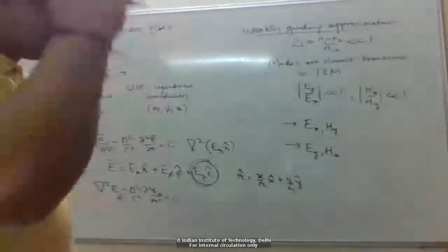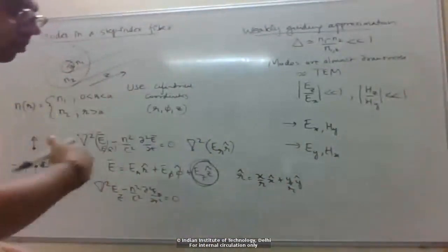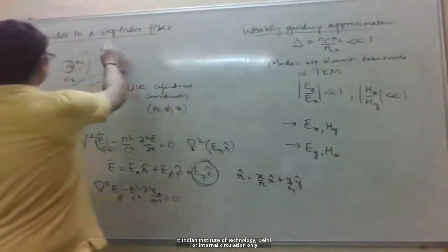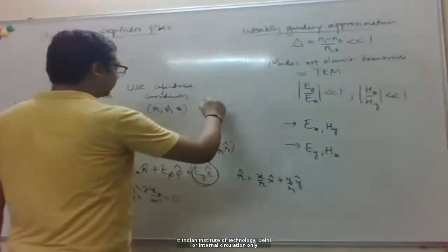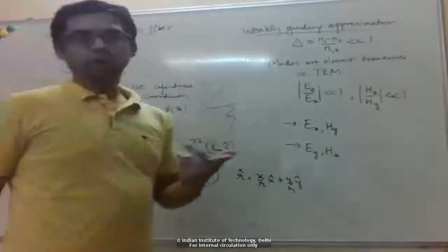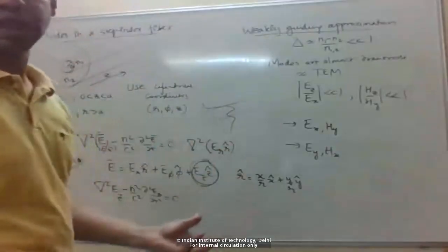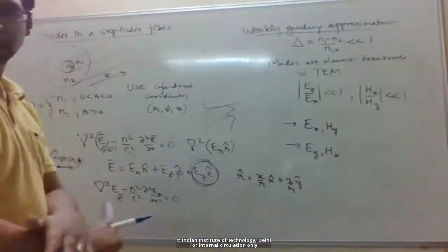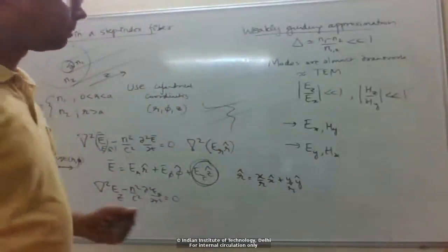So, can TEM waves exist? Of course, we saw that purely TEM waves can only propagate in homogeneous media. As soon as you have some structuring of the refractive index, and so any sort of waveguide where you have some field profile, then we saw that you can't have purely TEM waves. You could have maybe TE waves or TM waves, but not purely TEM. So that's the exact statement: if you have any waveguide, you cannot have TEM waves in them.